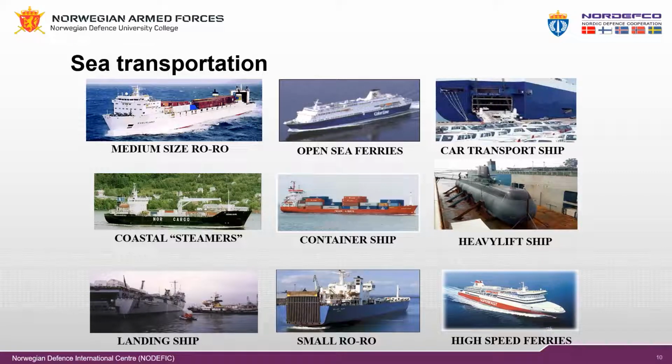The benefit of this type of vessel is that there are more offered in the market than the original ro-ro types. The disadvantage of using such a vessel is that it takes a lot more time to load and offload, and in addition, you need to be sure that the seaport cranes are able to handle your cargo.